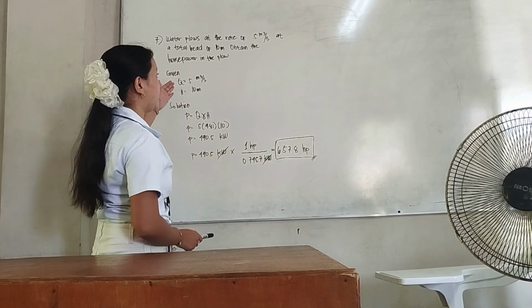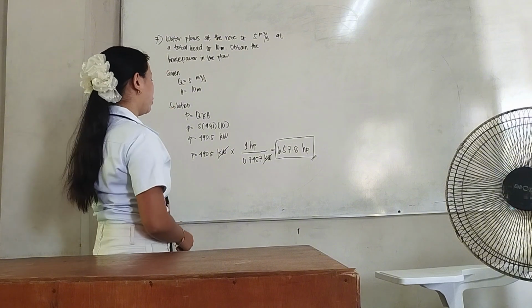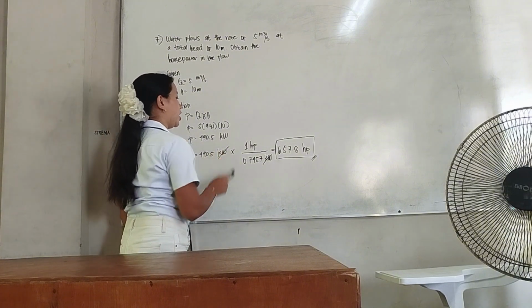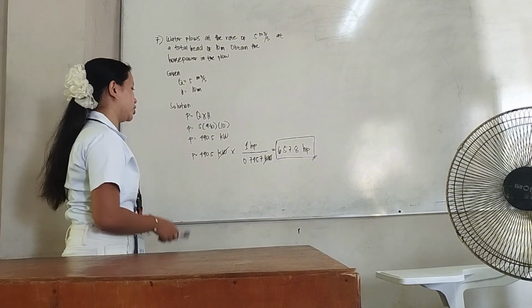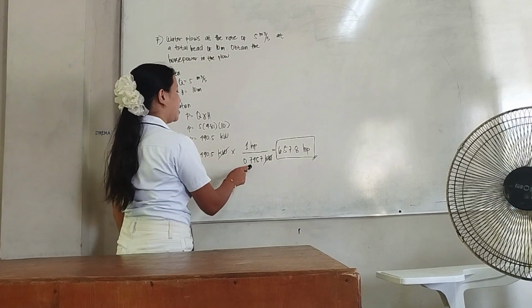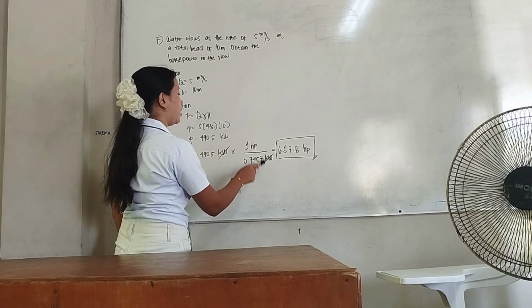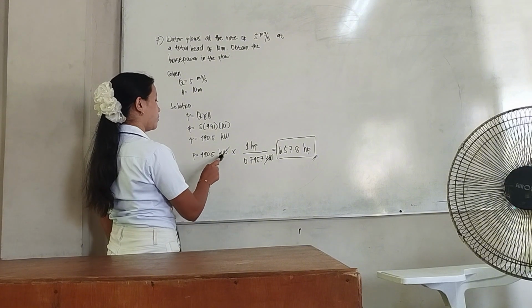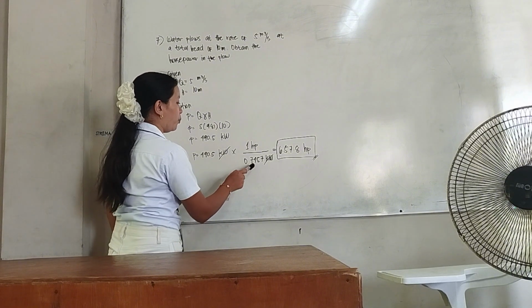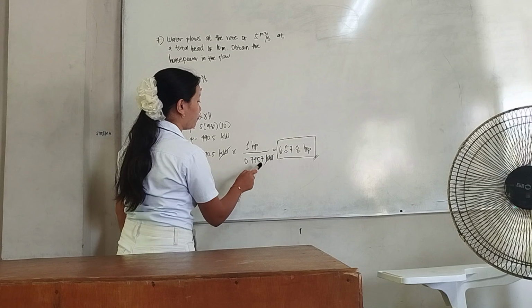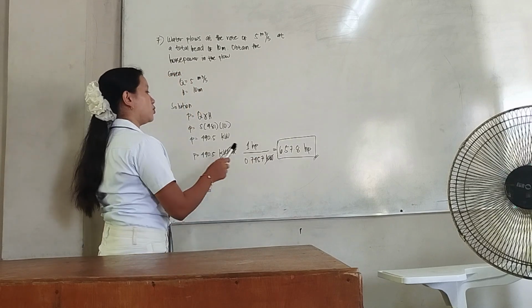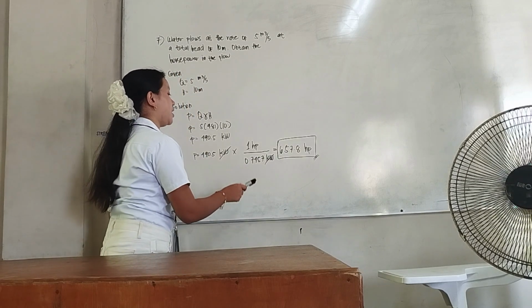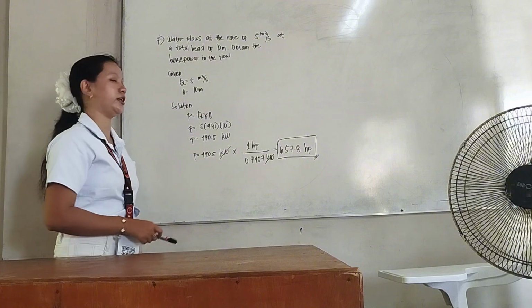So what is being asked there is to obtain the horsepower in the flow. So we have the answer in kilowatts, and we need to convert it into horsepower. So in 1 HP we have 0.7457 kilowatts. So, cross out the units. So 490.5 divided by 0.7457, we have 657.8 horsepower.